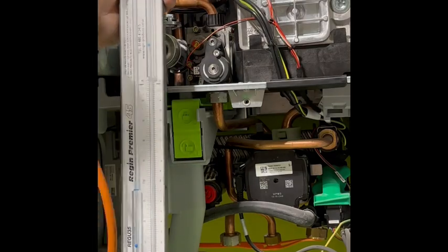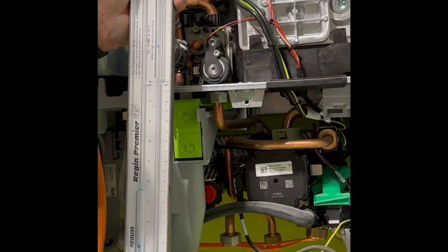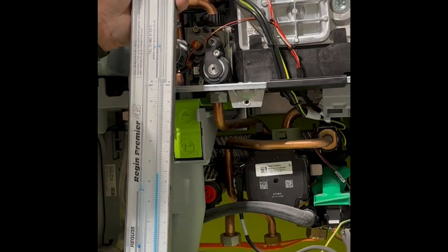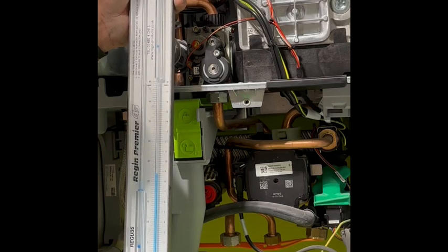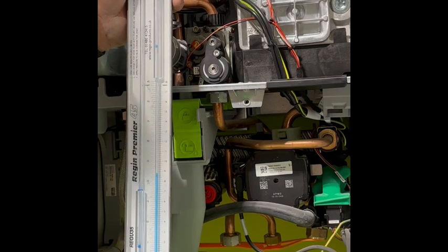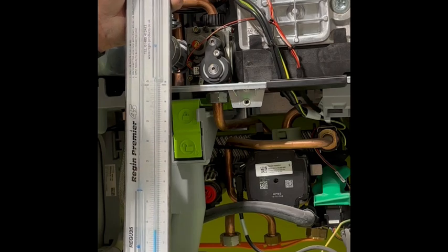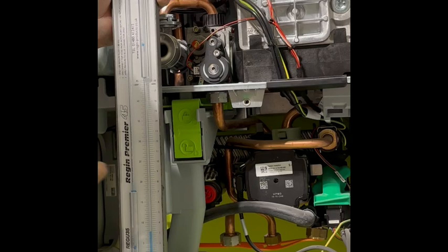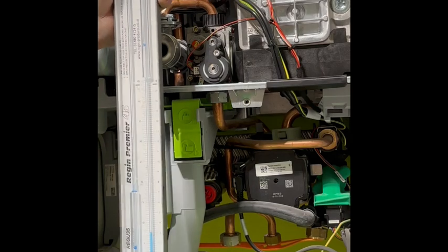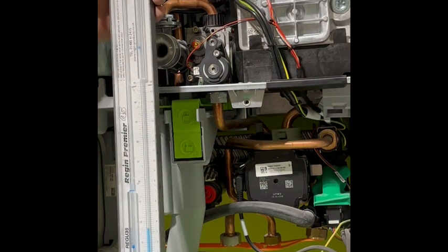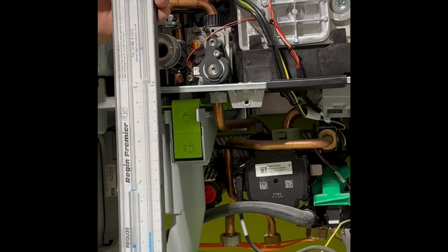So imagine we've got this connected to P1. We're going to have a standing gas pressure there. When that gas valve opens for ignition, we're going to see a movement in the gas valve. If it goes down to somewhere like that, we've got an issue. It should not be doing that. It should be dropping just a couple of millibar, maintaining a working pressure of around, textbook is